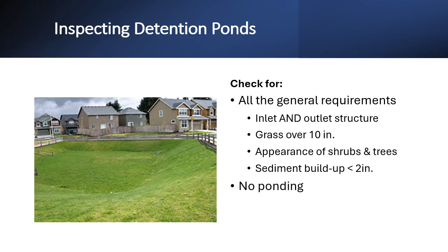Again, there should be minimal sediment accumulation with no more than 2 inches of sediment buildup. Also, there should be no standing water or ponding 72 hours after a storm. Again, if ponding becomes an issue, excessive growth of water-loving plants may start to appear.